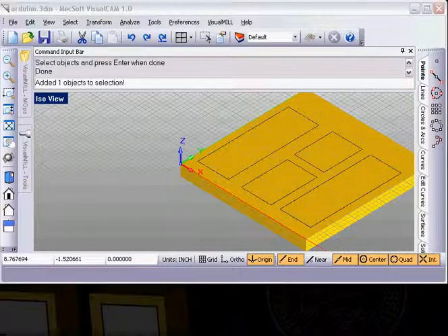We're going to be looking at the facing and pocketing toolpath pieces. We're looking at these together because they do almost the exact same thing. What you're going to find is pocketing is the one that you use most often. Facing is there, but it's not as useful. The difference between the two: facing will go outside of the lines that you're trying to cut. Pocketing stays within the lines.